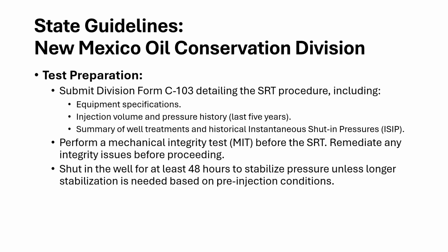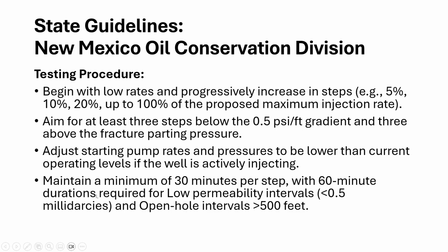They wish that you perform an MIT before the SRT. That is a mechanical integrity test. If there are any issues with that, you have to remediate any integrity issues beforehand. And again, they note that you shut in the well for 48 hours. They have general testing guidelines where you begin with low rates, typically 5% of the proposed maximum injection rate, but that may not be low enough these days.